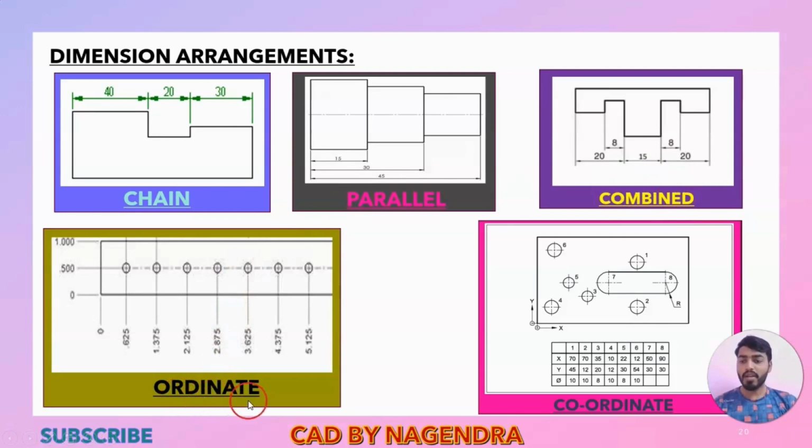Then ordinate dimension. So ordinate dimension is very important. What is meant by ordinate dimension? In this ordinate dimension, one origin point will be fixed, and for every point, the dimension should be calculated with reference to this origin point only. In ordinate dimension, the origin point will be fixed. For every next point, the dimension should be calculated with reference to this origin point only. So from here to this point in vertical dimension, here to here 500, here to here 1000, like that. Again from here to here this much, again here to here, here to here. The dimension should be calculated from here only.